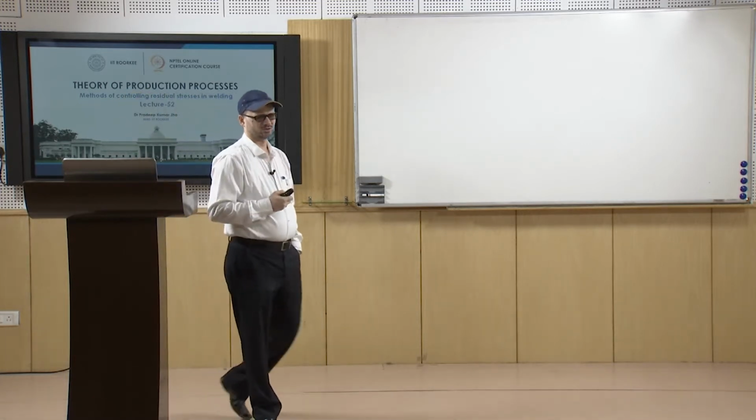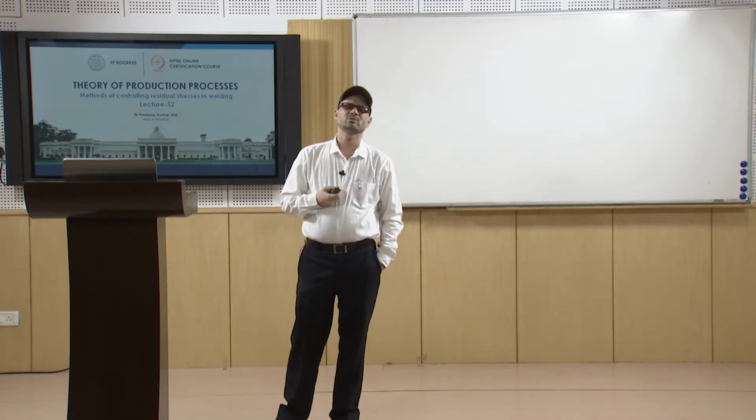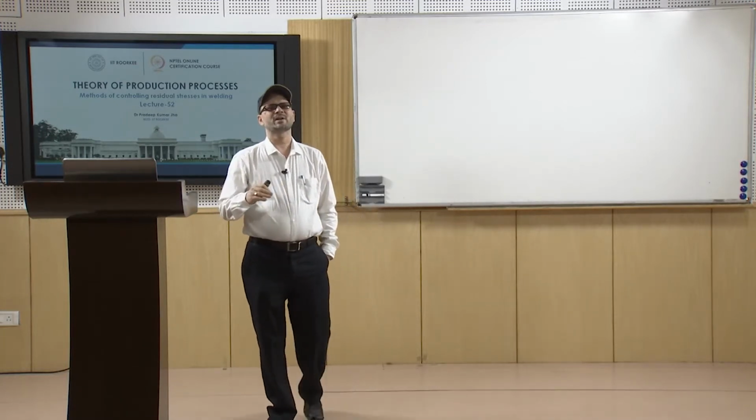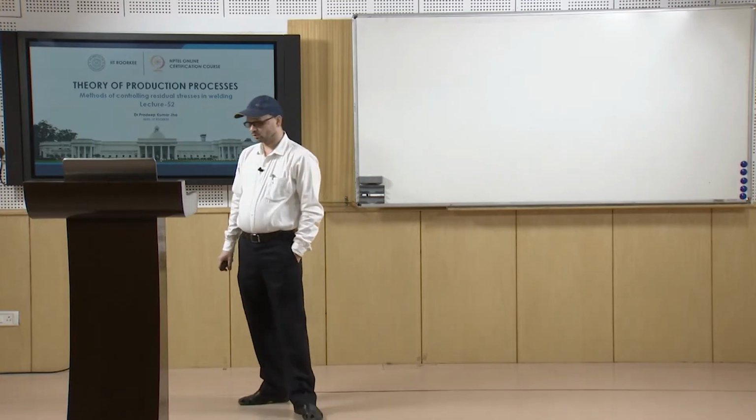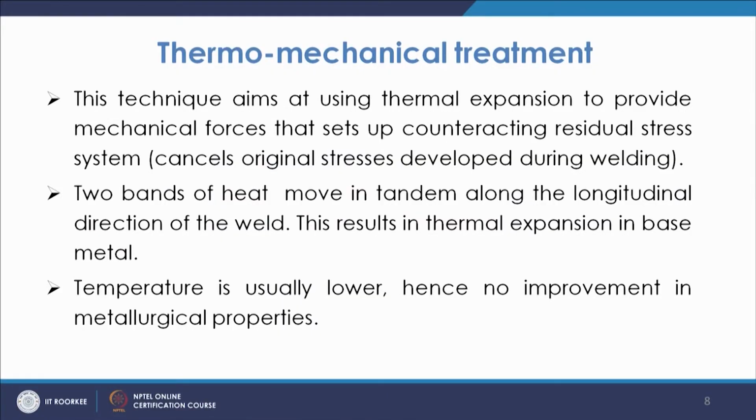Another practice to remove these residual stresses is the thermo-mechanical treatment. In this case, we use the thermal expansion to provide mechanical forces that set up a contracting residual stress system and cancel the original stresses developed during the welding.